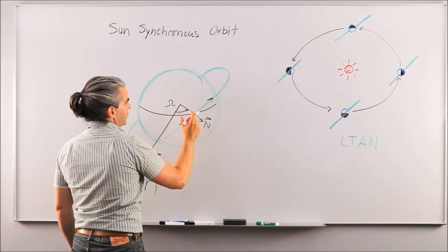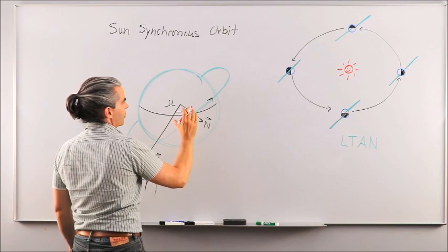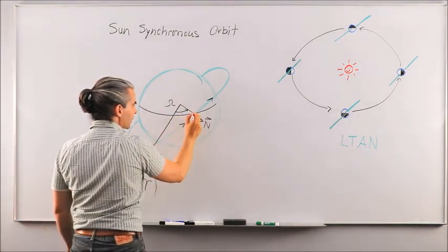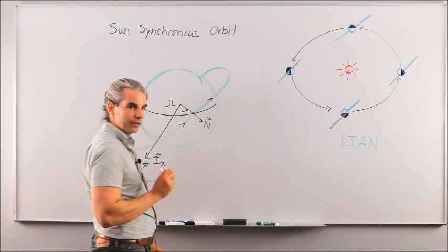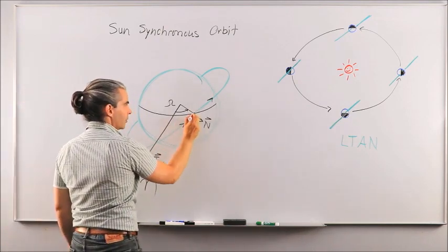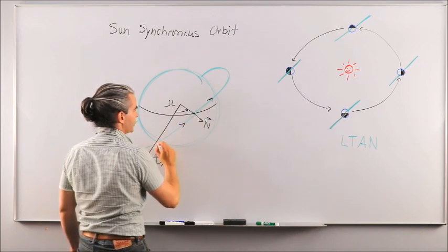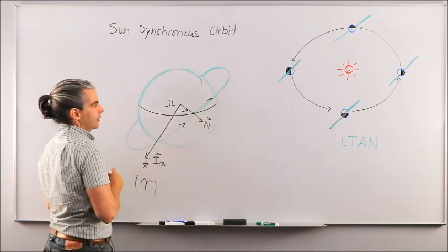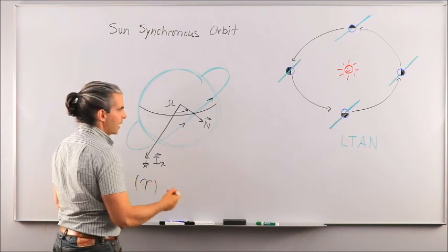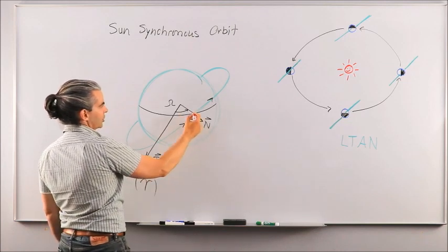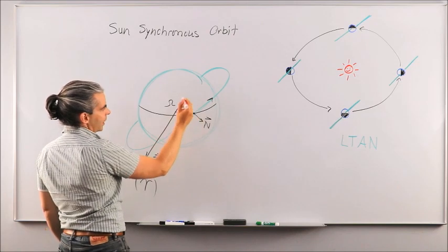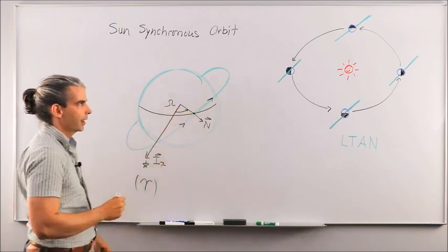So because the Earth rotates underneath the orbit, that local time of ascending node keeps shifting, because the local time at that particular point along the equator when the spacecraft goes from south to north could be noon, and then an orbit later could be 2 p.m., and then 4 p.m., 6 p.m., then boom, you're in the shadow, and then sunlight comes, and then 2 a.m., 4 a.m., 6 a.m., and so on and so on, okay?